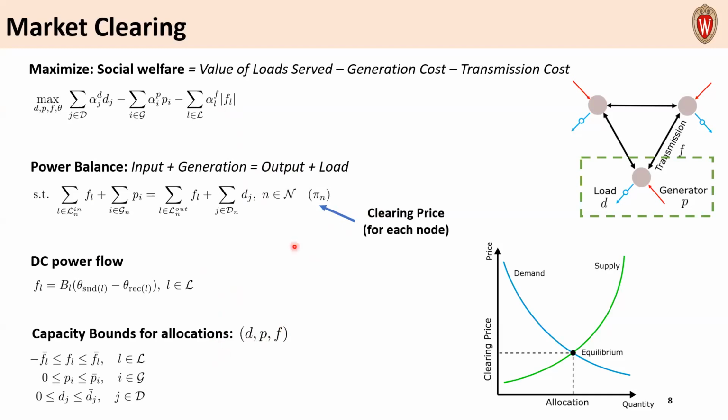One thing I want to note here is that we have a cost term for transmission in the objective function, which is not a common practice in power system optimization. We add this term in order to highlight the relationship between the virtual links and transmission lines. I will show more details on this later when I talk about virtual links. But in practice, the bid prices for transmission lines are mostly set at simply 0.